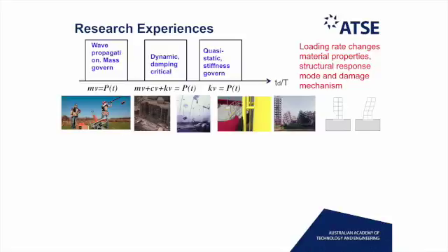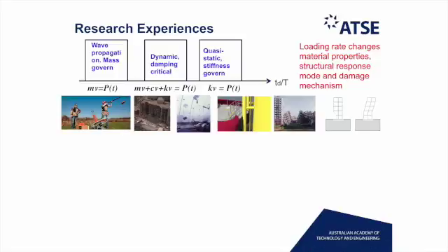So my research covers the entire spectrum. If it's static, it's covered by displacement, which is Hooke's law. If it's very, very fast, it's covered by wave propagation, which is Newton's second law. In general it's in between. I put there one typical Oklahoma building collapse by blast loading. The building stands straight. In a typical earthquake collapse, the building actually shifts around. It's displacement governed. So I cover this entire spectrum, different loading rates from static to very, very fast blast.